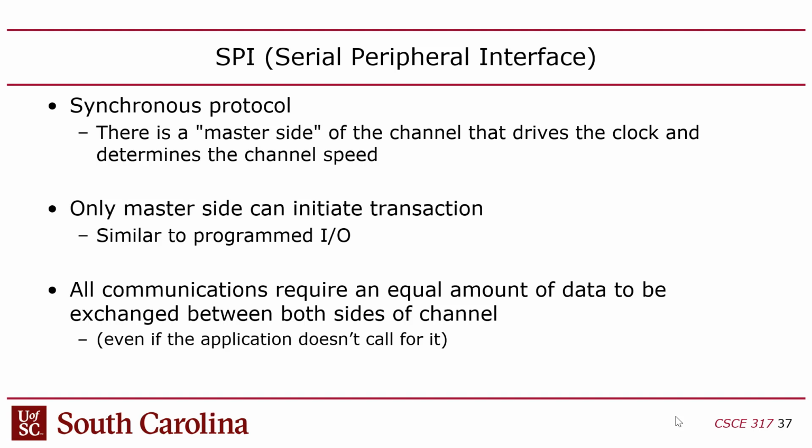Okay, so why would we choose a parallel bus over a serial bus? What's the deal? What's the advantage? Well, parallel buses require multiple wires. And that's a lot easier to do on a chip or on an FPGA than it would be on a circuit board. Because if you put multiple wires on a circuit board, it's very difficult to have all the bits arrive at the same time.